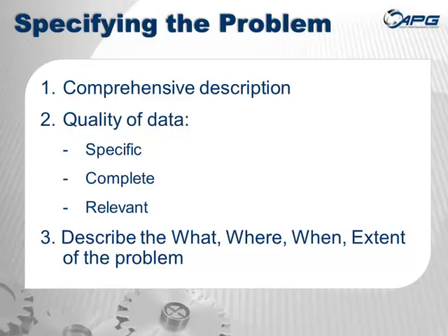So for instance, I was working with a nuclear power plant some time ago, and they had a problem with a backup power generator. And we spent the better part of a morning just describing the defect itself. It was a subsynchronous type of vibration, very specific frequency and amplitude, and it took about a page to get it all down there and describe the problem. It was very, very specific, and that was very helpful in us solving the problem.